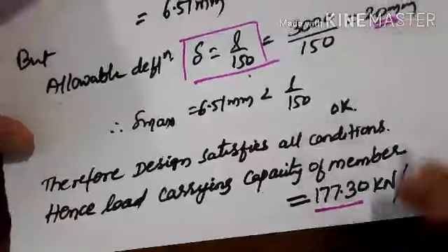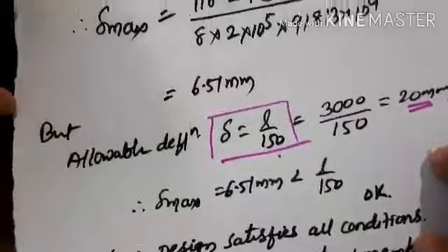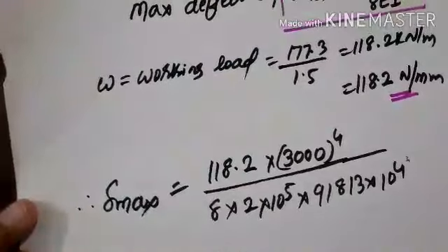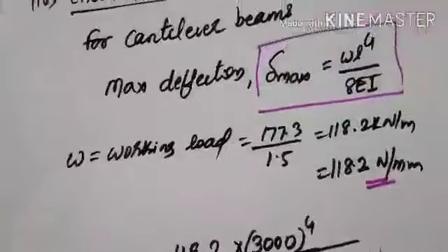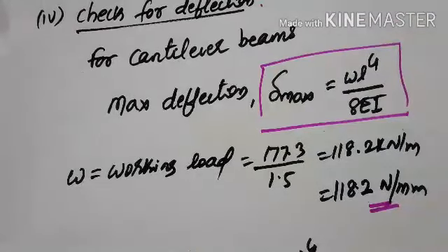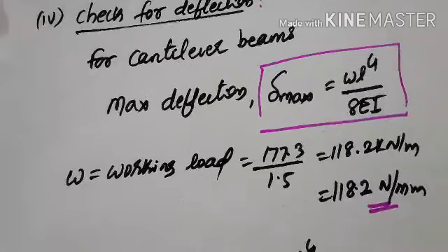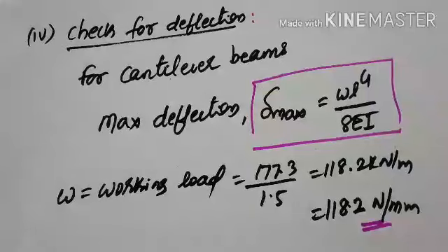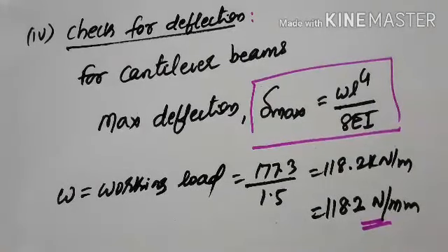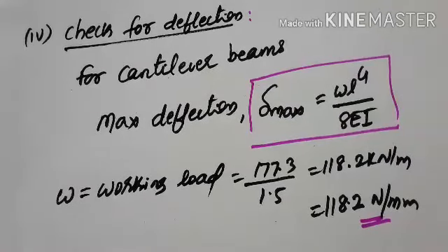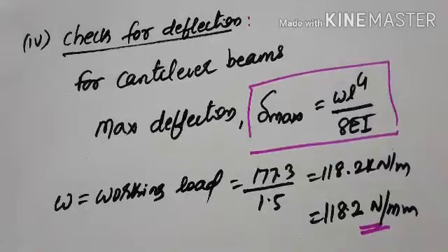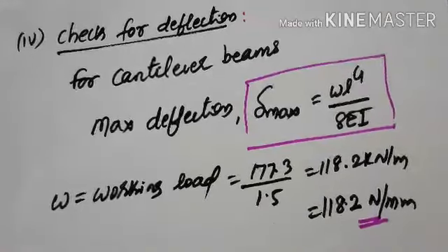So this is how to calculate the bending strength and do the checks step by step: check for shear, check for web buckling and web crippling. Try to refer to previous lectures where we discussed the bending strength calculation, how the web buckling strength and web crippling strength can be calculated, and use those equations. Or else refer to IS 800-2007 where you will find the equations. I hope you understood this.